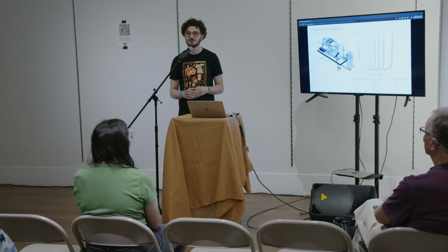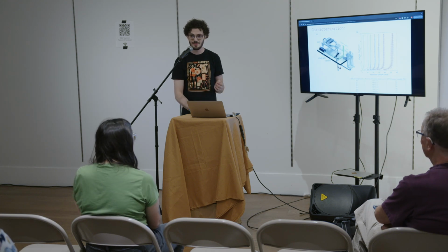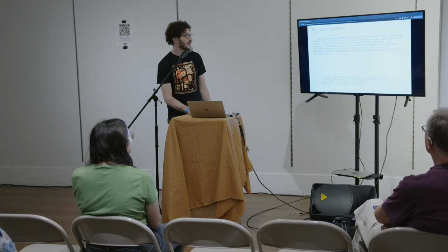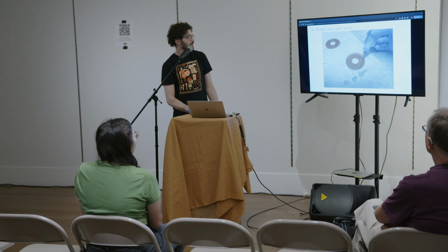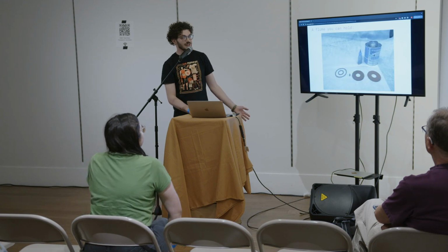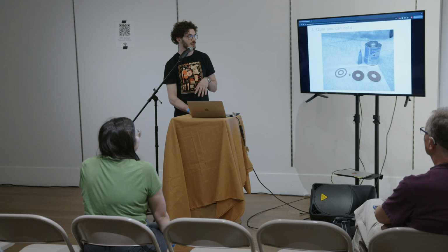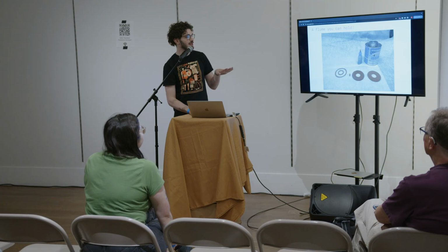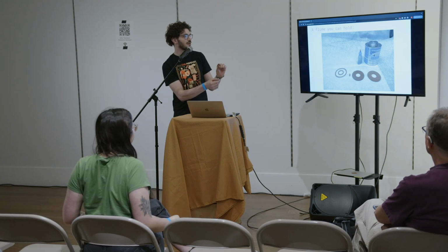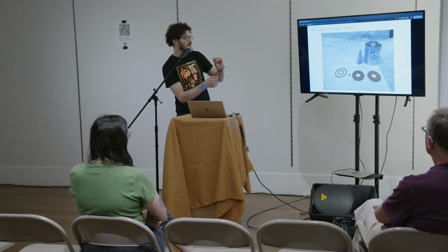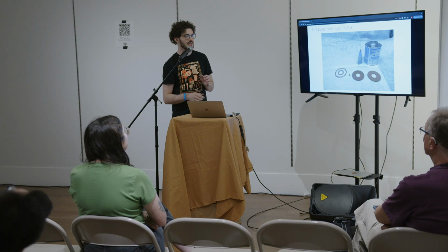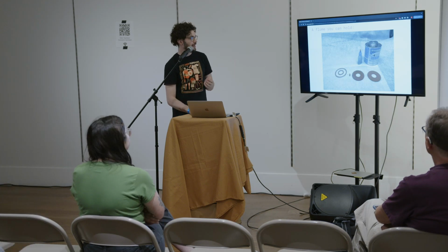If there's no other questions, I'll show you how to make fidget spinners. The fidget spinners are fun because you can use the laser cutter because we're not actually bonding the edges. We're only bonding the surfaces. So if there is any crazing, it's not really a problem. We start with these sheets that will laminate together. The top and bottom are 1/16 inch, and then the middle slice is 1/8 inch or 3mm acrylic.